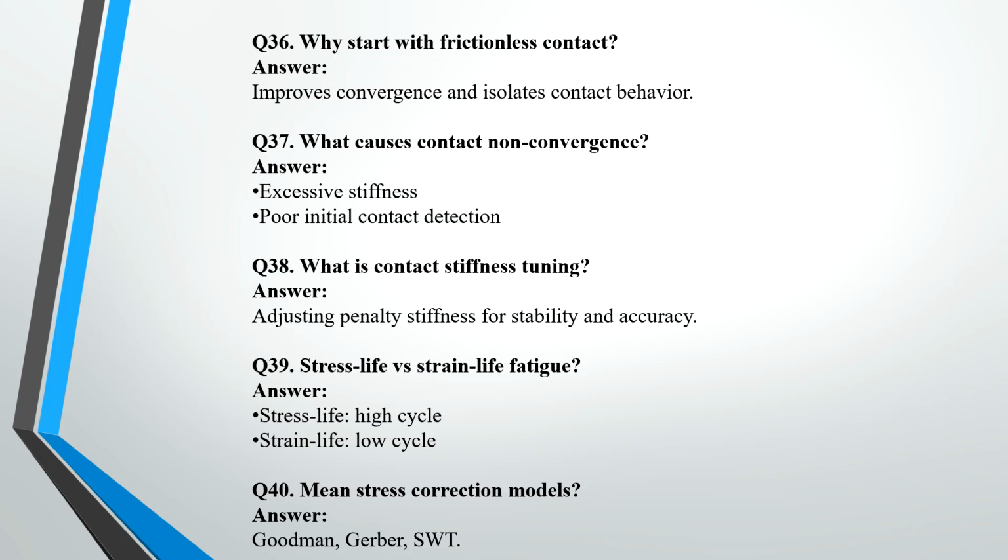What about fatigue? This is a common question they ask. What is stress life versus strain life? In high cycle fatigue, we use the stress life approach. In low cycle fatigue, it's a strain based approach. What are mean stress correction models?